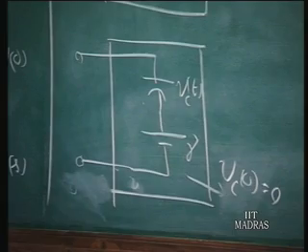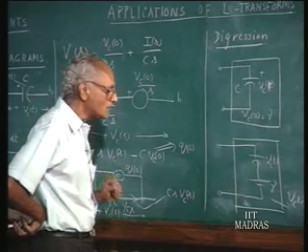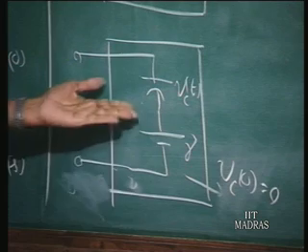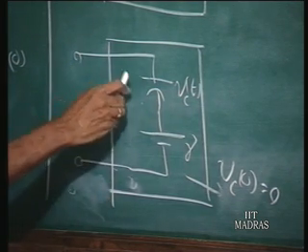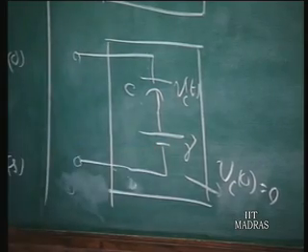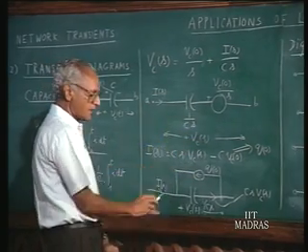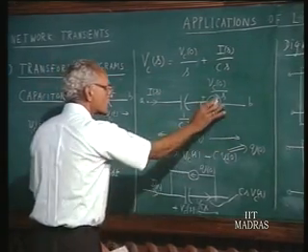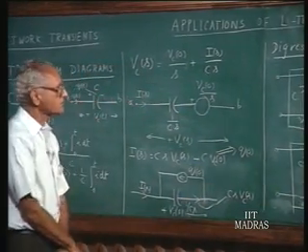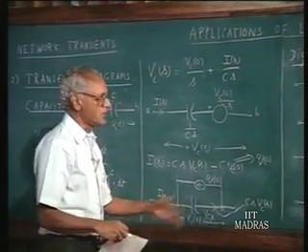And therefore, if you have a capacitor which is carrying an initial charge and therefore initial voltage gamma, we can represent this as an uncharged capacitor in series with a source. And if you take the Laplace transform of this, this capacitor C has 1 over Cs as the generalized impedance, and a source which is gamma over s. So that's exactly the situation that we are having. Initial voltage across the capacitor can be represented as that of a source, and that source, a DC source, will have a transform like this. So these two tie up like this. Now, we can also think of an equivalent current source representation that will lead to this, but we will not do that.